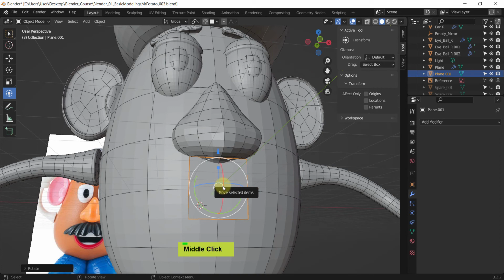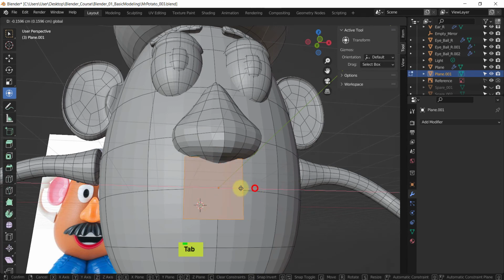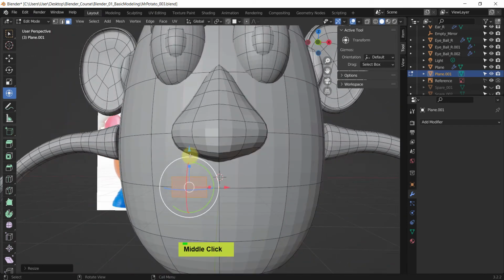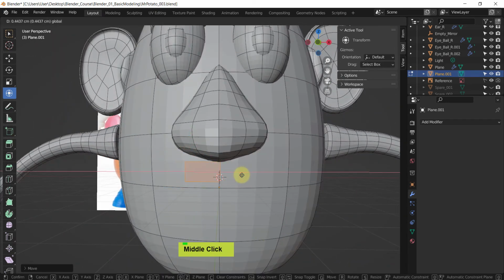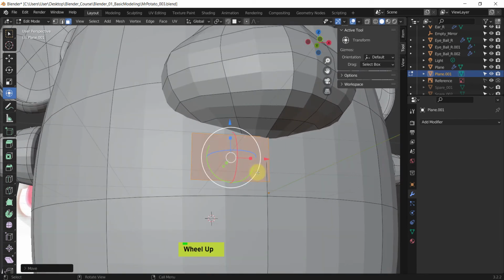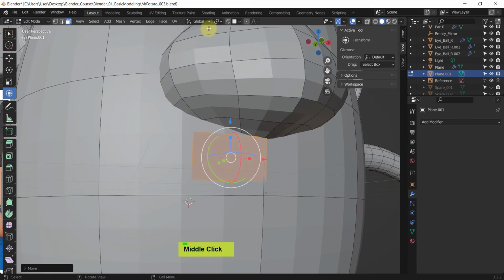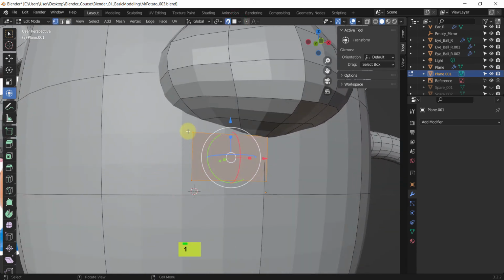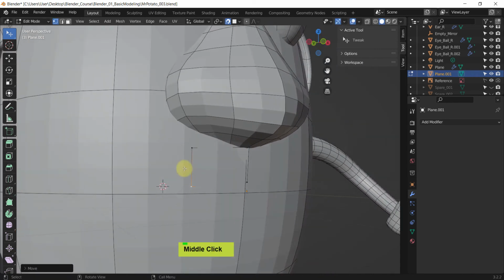What I will do is I will go into edit mode, select the face, and just move it aside and scale it along the z-axis. Okay, just move it up, move it here in the middle. Okay, so we have 4 strands, so it can start from here. And what we do need is snap turned on, and snap is set to project on the surface, so that's working fine. Polygons should be selected. Let me use tweak and snap the points on here.